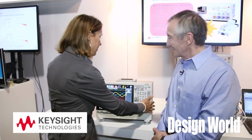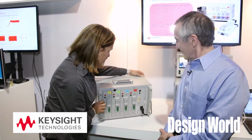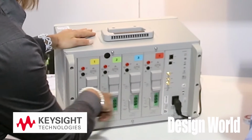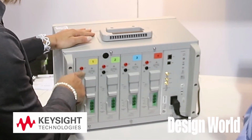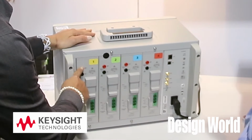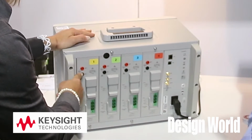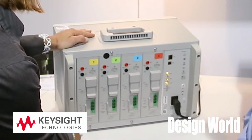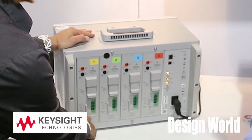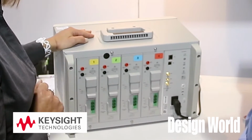So I think we should start back here to show how it is different from the back side, because what we have here, we have 4 power channels. Each power channel means that it measures voltage and current, each channel. These voltages are isolated up to 1000 volts. And current, we can measure a couple different ways. We have internal shunts. Each channel has 2 shunts, 2 amp shunts and 50 amp shunts.